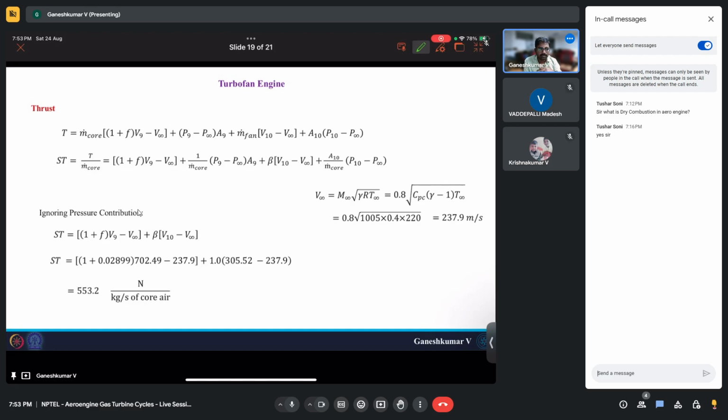So if you make all these appropriate changes, then finally when you find the thrust, you need to add the additional thrust contribution from the bypass stream. Okay, those are the few differences that you will observe when you do calculations from turbojet to turbofan, especially for this case, which is forward fan and mixed single spool engine.